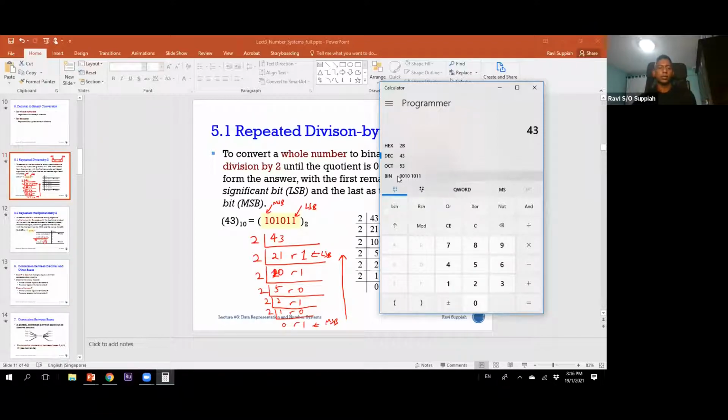The reason why you see the 2 zeros in front is because it always represents the answer in groups of 4 bits or 8 bits. So since the lower 4 bits and then there's another 2 bits, it automatically puts another 2 zeros in front. So that is why you see the first 2 zeros. But that does not affect anything because, like what we saw just now, the weighted position only takes significance when you multiply it by a 1. Correct, for binary. When it's multiplied by 0, you still get 0 anyway.